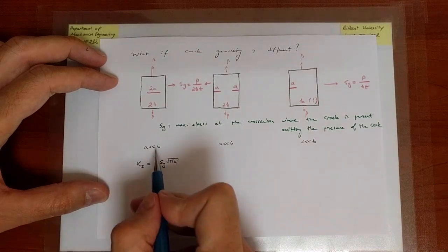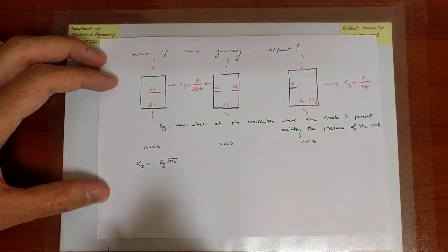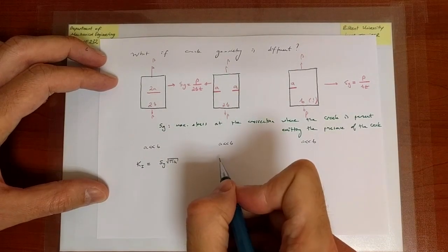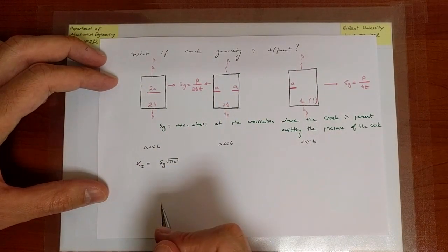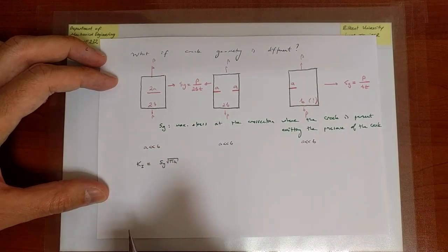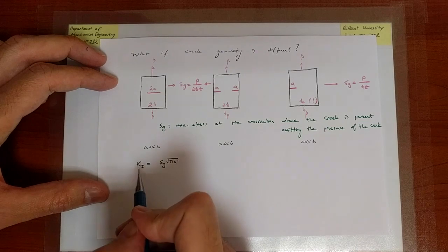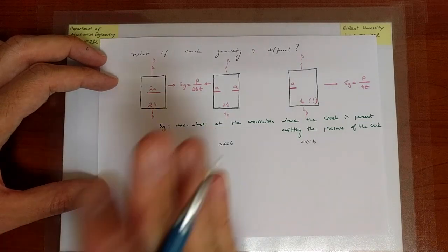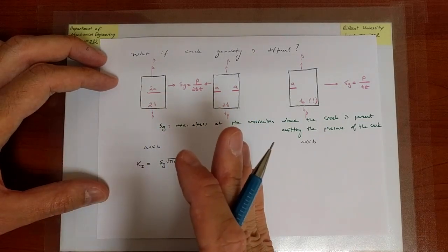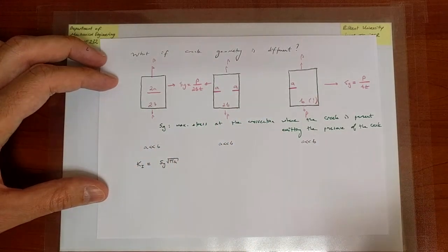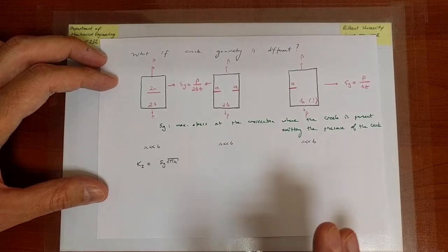Okay, that's what we have already written in the previous slide. Now, this case is a different case. It's not the same crack geometry. And because it's not the same crack geometry, it turns out the expression for K1 differs. Remember, what does K1 do? It goes into the stress distribution expressions in terms of the radial distance, cosines and sine thetas, the orientation from the crack tip, etc.